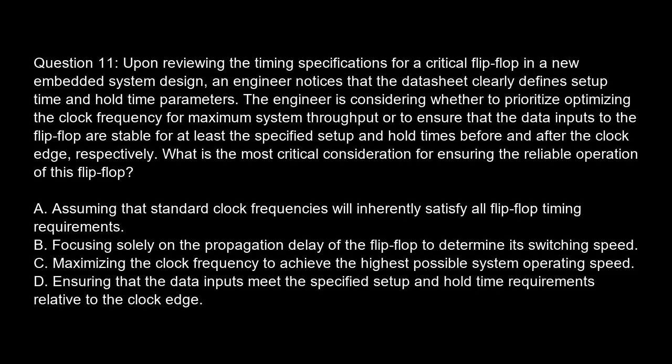Question 11. Upon reviewing the timing specifications for a critical flip-flop in a new embedded system design, an engineer notices that the datasheet clearly defines setup time and hold time parameters. The engineer is considering whether to prioritize optimizing the clock frequency for maximum system throughput, or to ensure that the data inputs to the flip-flop are stable for at least the specified setup and hold times before and after the clock edge, respectively. What is the most critical consideration for ensuring the reliable operation of this flip-flop?